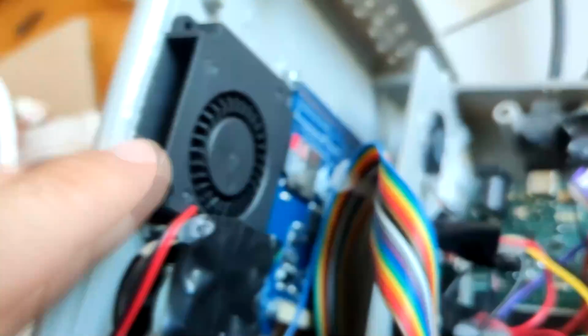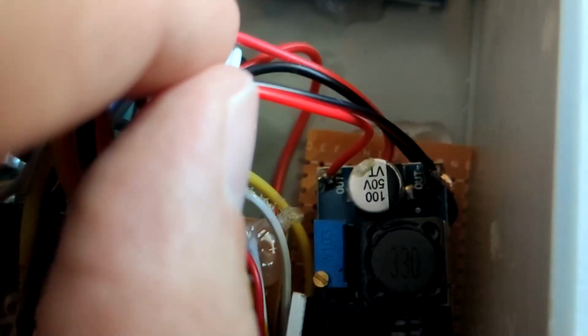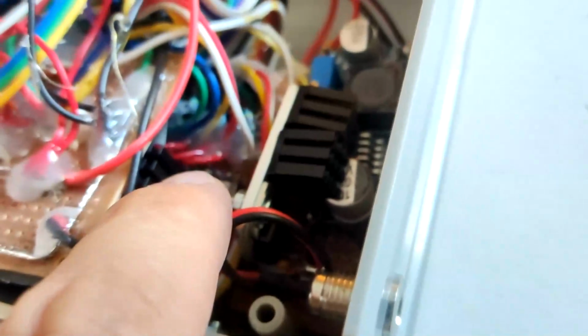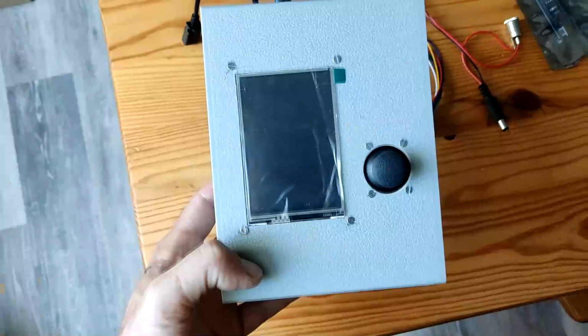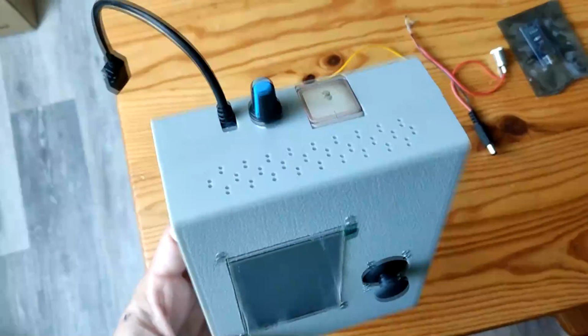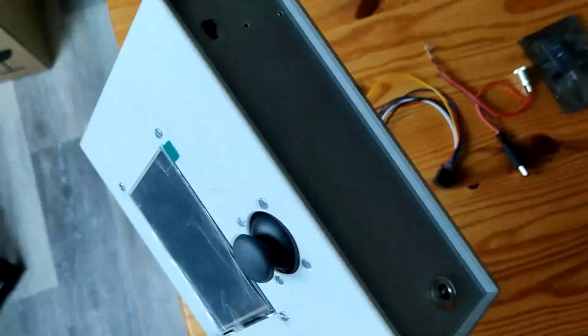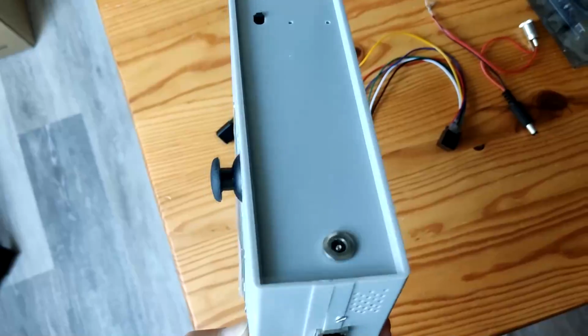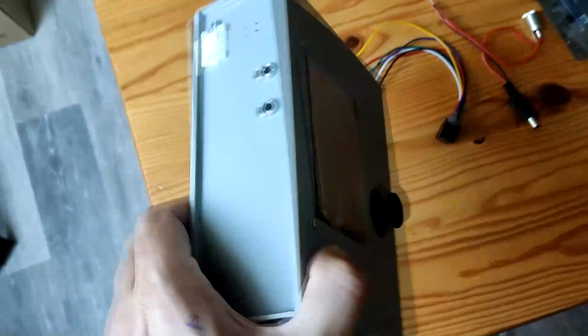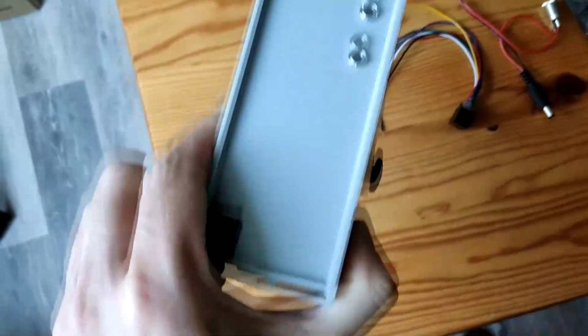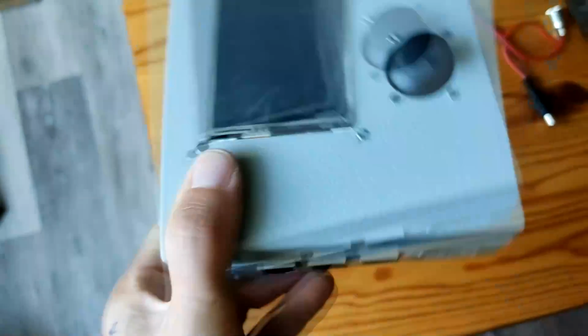I've also installed a 5 volts fan. This is a radial fan mounted directly on the 5 volts buck. I've made a hole on the side for extraction, and on the bottom side you have the aspirating holes and the space between the RJ45 connectors to cool the drivers and the power supply board. The holes on the top I resealed because I don't need fresh air coming from the top, because there is nothing to cool. And here we have the box completely finished.